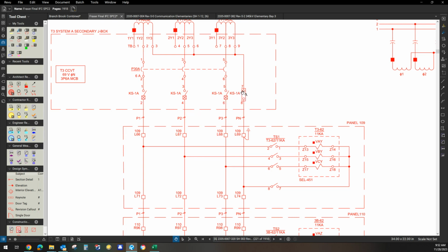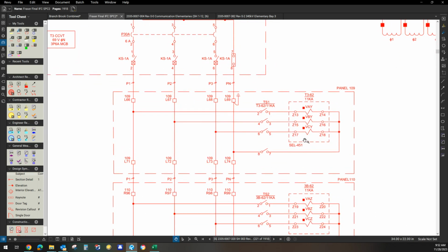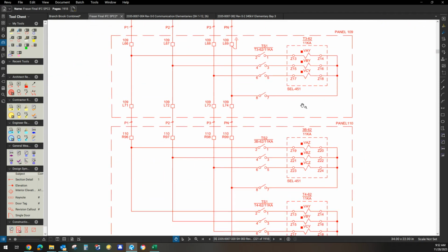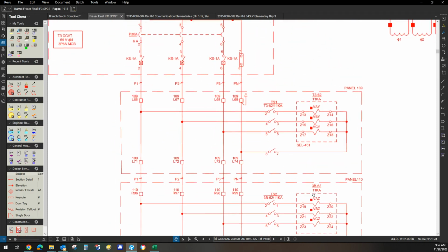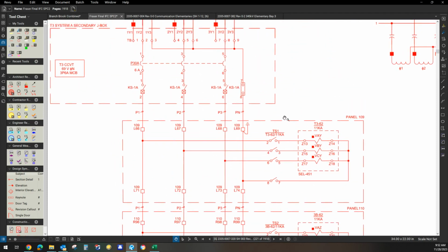But if you were to accidentally open the neutral, and you have these phases closed in, and the CCVTs are energized, the device that's reading this voltage, and this one is an SEL 451, these relays will lose their reference and the voltage will float. So that is why they eliminated the knife blade here and put the slug in here.